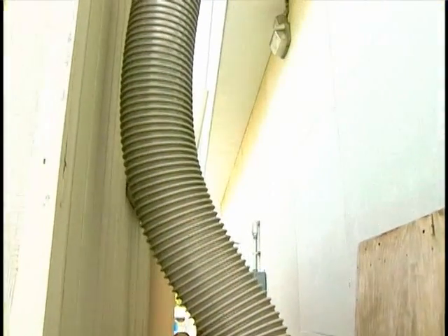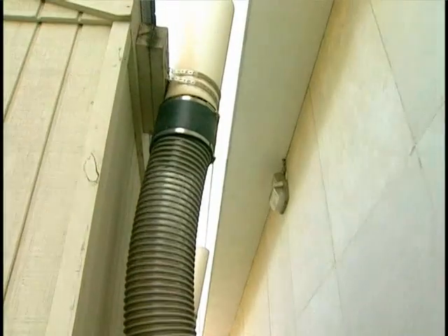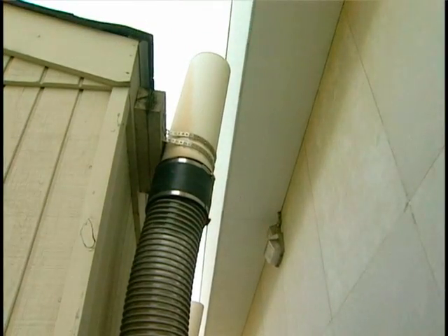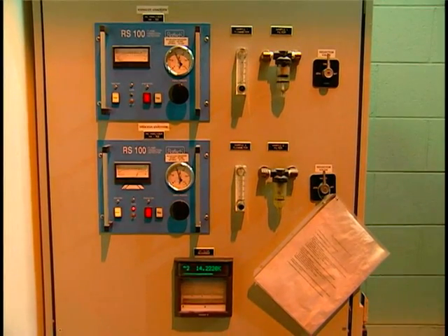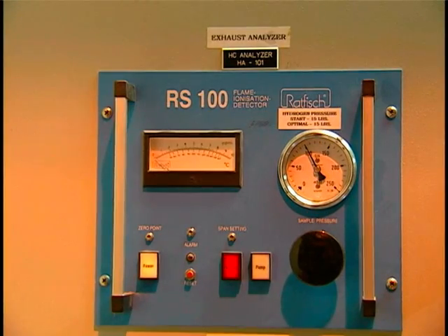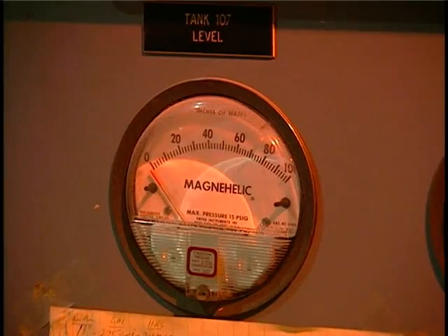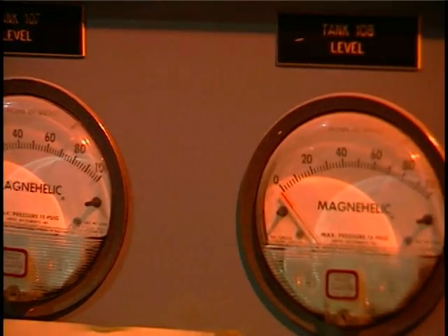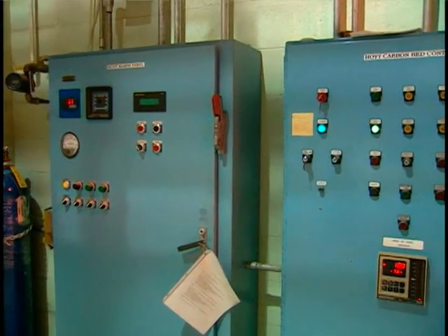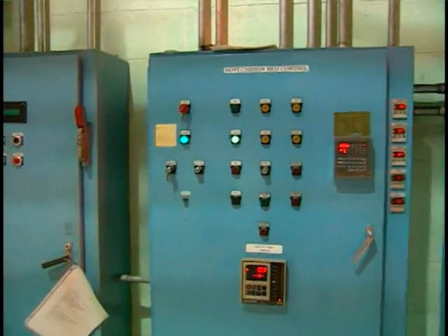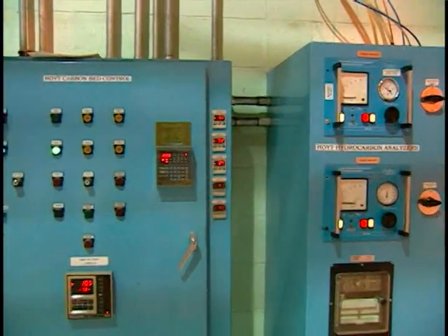There should be two goals in any field inspection. First is to evaluate the source's compliance with any rule-specific monitoring requirements and with the provisions of the Title V permit. In addition, parameters that influence performance should be evaluated to see if there are shifts from their baseline values that could indicate reduced control device efficiency.